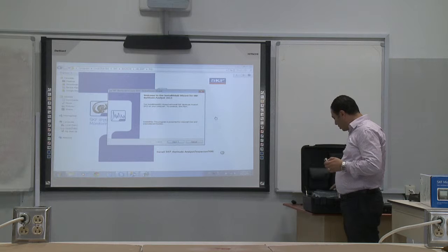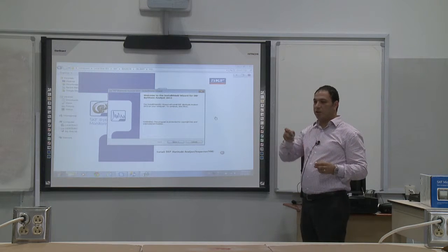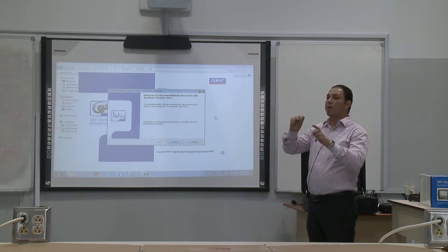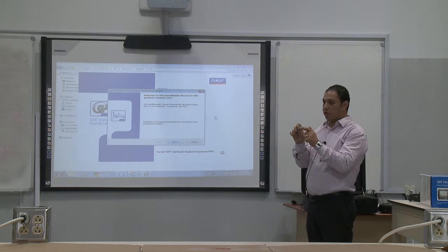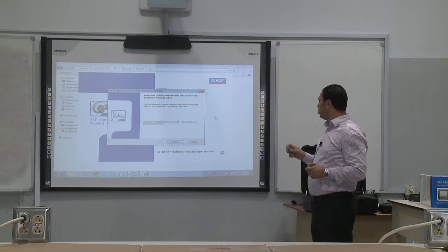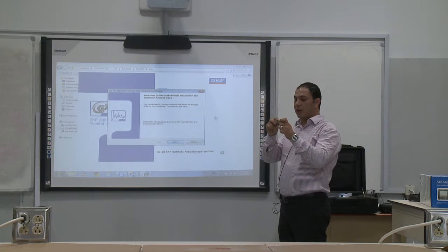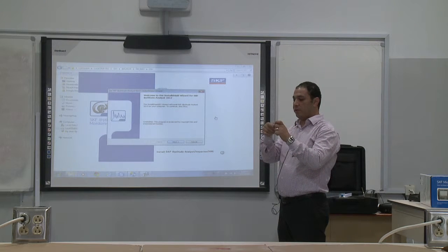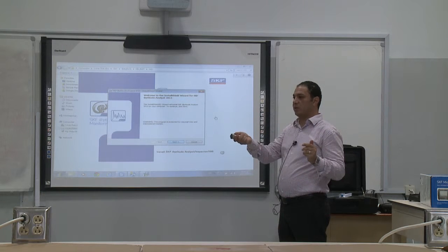Each of these 2 accelerometers comes with a stud. So you can mount it using a stud. With the stud, you can mount it to the equipment, or you can mount the stud to the magnet like here, and then use the magnet in the measurement.